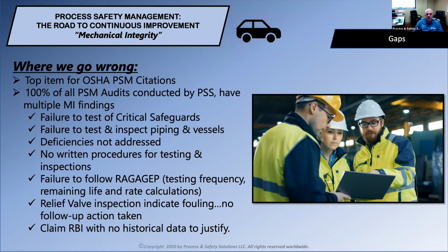Also, relief valve inspections indicate failing but no follow-up action. I don't know how many times I've looked at third-party relief valve inspections, and they will indicate failing or fail to pop, or some other indication within the report itself that would indicate to me that there should be some follow-up work done. Follow-up perhaps to increase the frequency so that the next time that valve is inspected, it doesn't have those fouling issues or it doesn't have that damage that was indicated in the report.